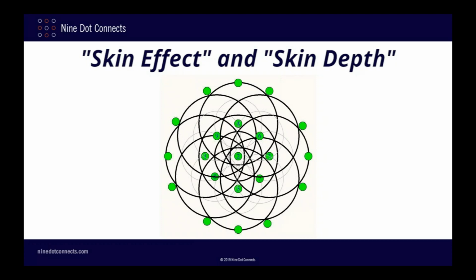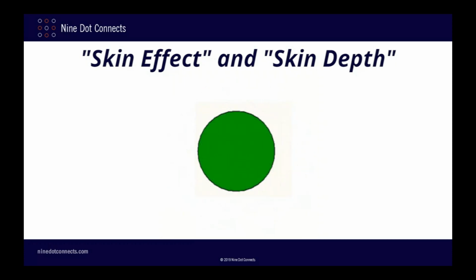Now, the astute observer may be wondering just how, if the current flow increases the impedance, but the impedance reduces the current flow, why does this even work? Well, as Dr. Ian Malcolm says, nature finds a way. It turns out to be a balancing act where just enough current flows to create just enough of a magnetic field to increase the impedance just enough to force the current to flow closer to the circumference of the wire. If we keep taking things to the limit, mathematically speaking, and keep adding an infinite number of infinitely small wires, we end up with a solid piece of cylindrical copper, commonly known as a bigger piece of wire.